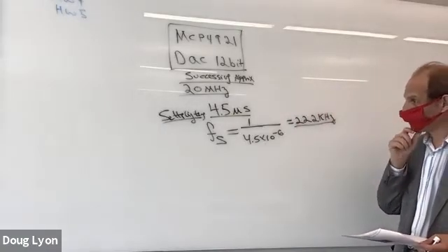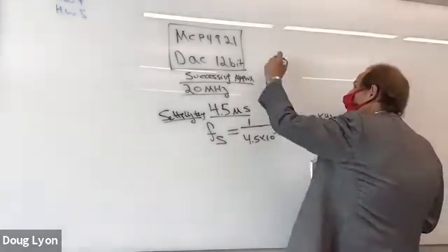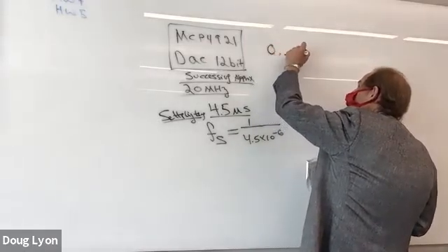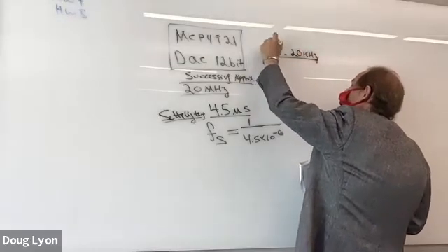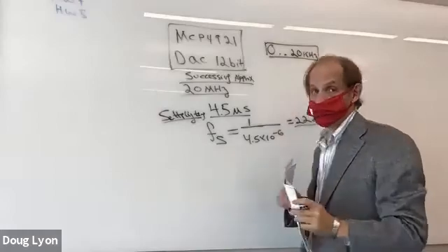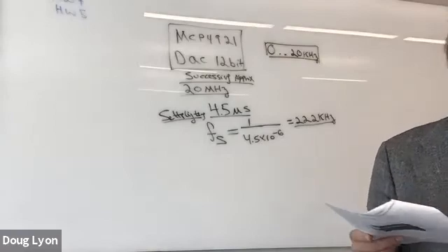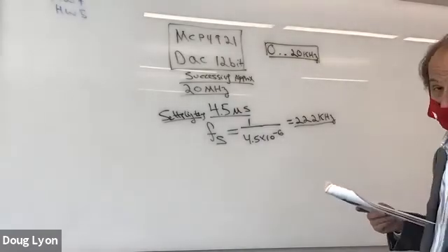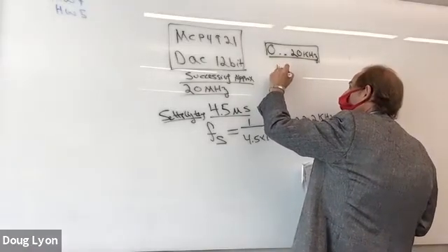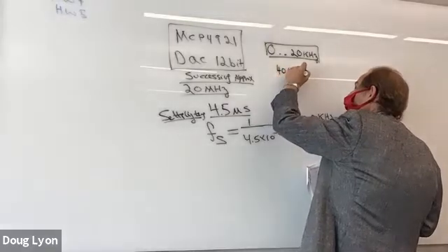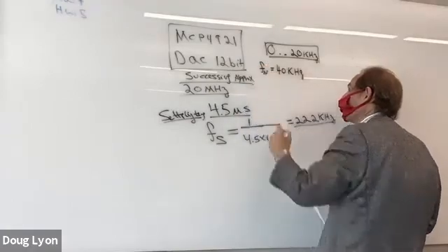Now, if you're dealing with audio, it's got a range which goes from 0 to 20 kilohertz, or thereabouts. If you're dealing with a Nyquist sampling theorem, you have to sample it twice the highest data rate you plan on reconstructing, at a minimum. So at a minimum, we'd like to sample at 40 kilohertz. And I'll write S sub n for Nyquist.